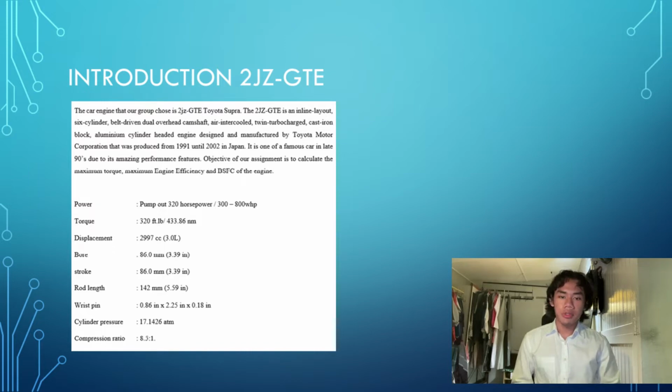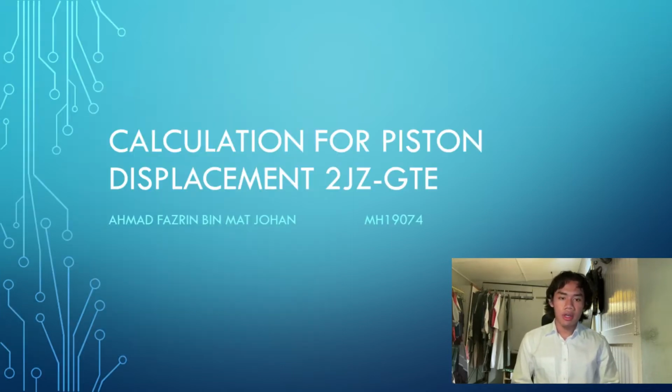We have researched and done the calculation for the engine specification and we get the compression ratio equal to 8.5, the piston displacement of 99.6 cm3, the piston cylinder bore, and also the length of the piston stroke is 8.6 cm, the length of the piston rod 14.2 cm, and the air fuel ratio AFR 14.8. All of these specifications have been updated in the formulated Microsoft Excel given, and here are the values that we got.